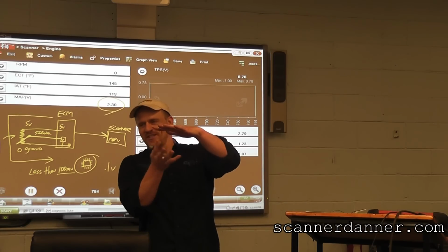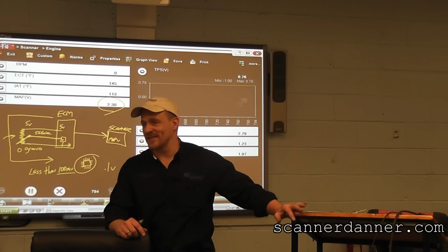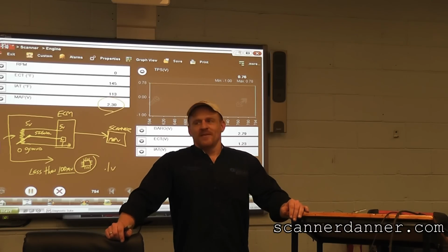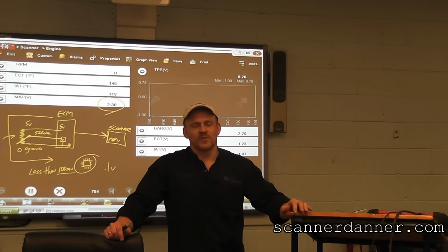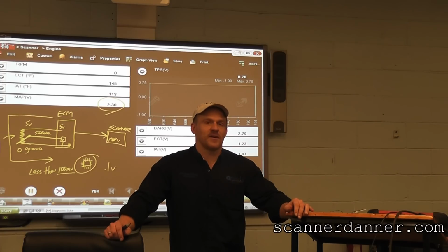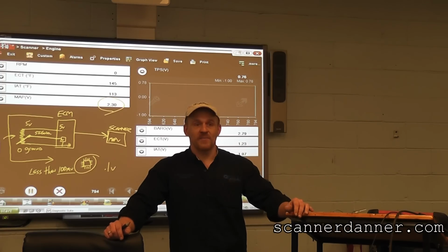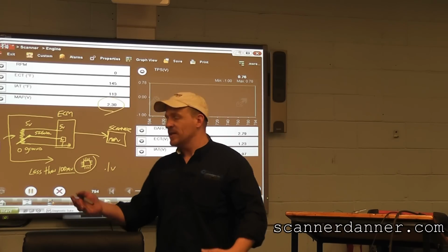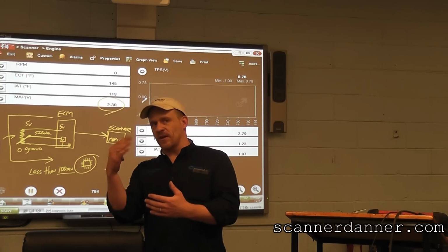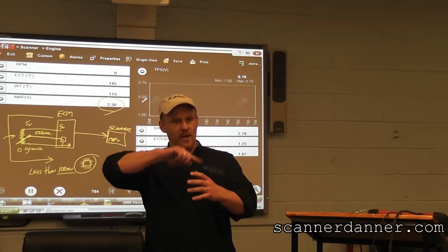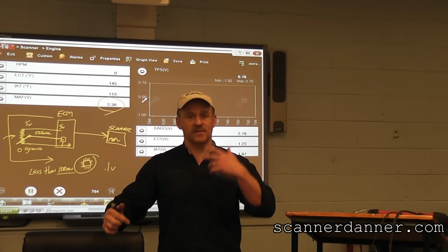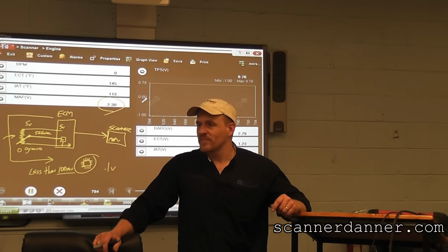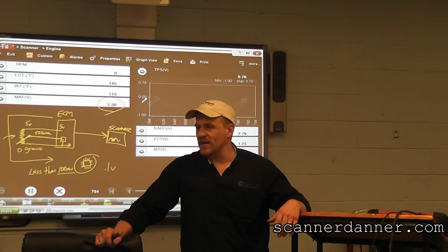Crystal, pressure this side, pressure on that side. That's only one way it's done. Ford does it that way. Other ones use a flexible silicone diaphragm, and as the diaphragm flexes, its resistance changes. It's a more simplified version, and it works similar to this. But rather than being a movable resistor like a wiper moving on a slide like a TPS, it is a flexible diaphragm. Sorry. That doesn't actually generate the voltage directly. Correct. It modifies a signal.